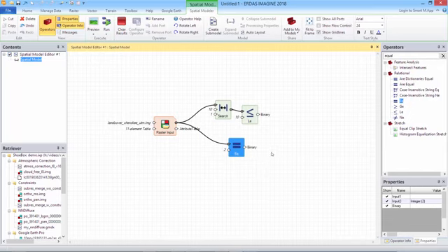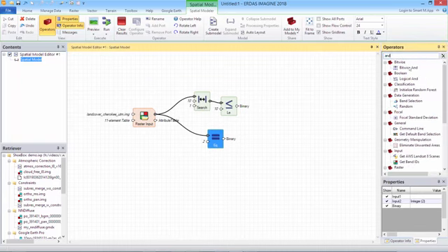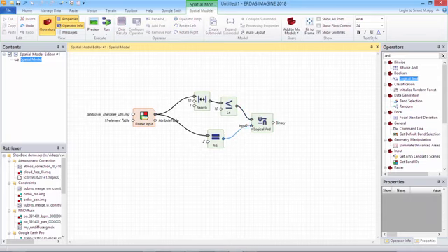What we want to do next, obviously, is evaluate locations where both criteria are true, that it is both a forestry area and it's within 150 meters of water. So that is a logical AND. We want both to be true. So I'm going to pull in the logical AND function operator, bring in both these tests. So both tests must be true. This must be true and this must be true. If both are true, then we get a binary 1, or otherwise it's 0, false.